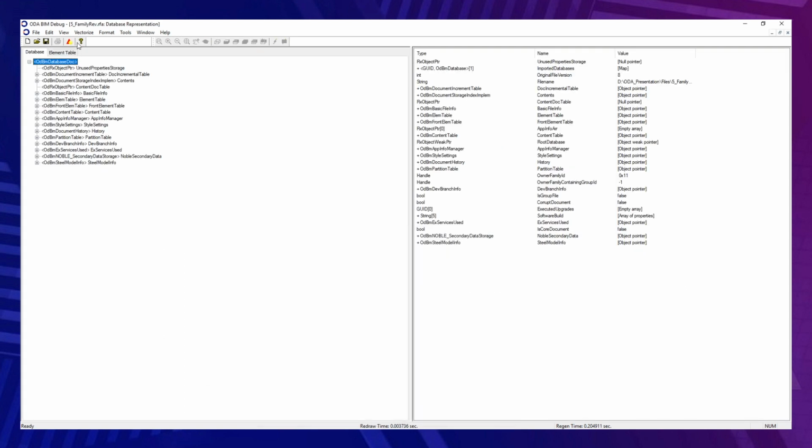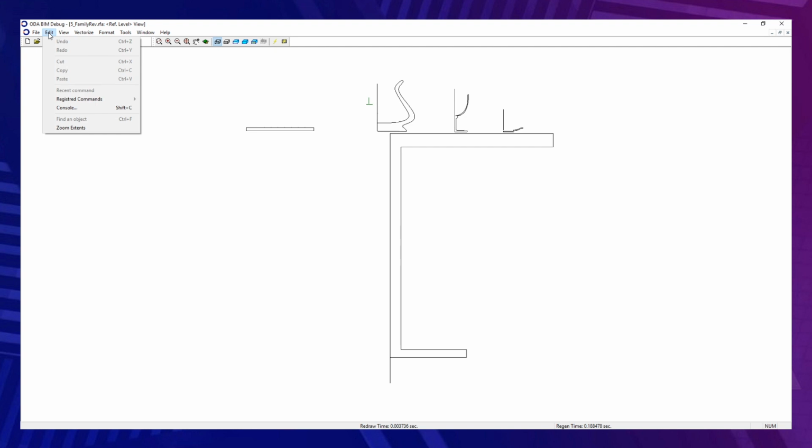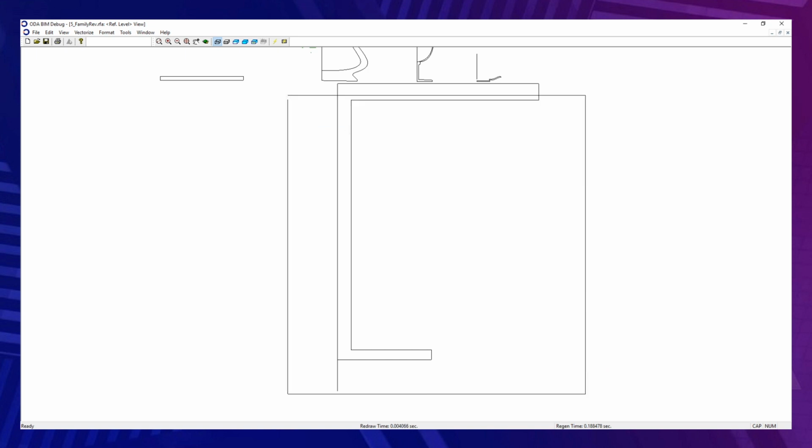And other elements which we are going to create are extrusion and revolution elements. So we also created a file for showing this possibility. Here we have one loop for extrusion and several loops for revolution. The file also contains a set of materials for different elements. So first of all, we created an extrusion, and we continue to create revolution.